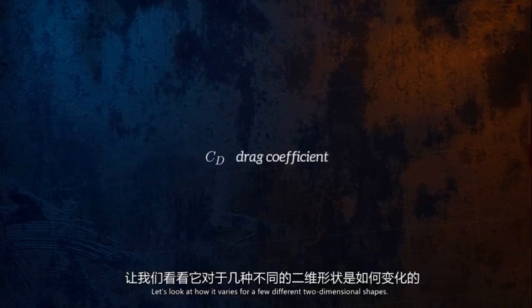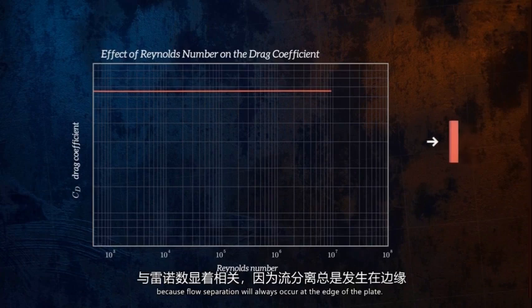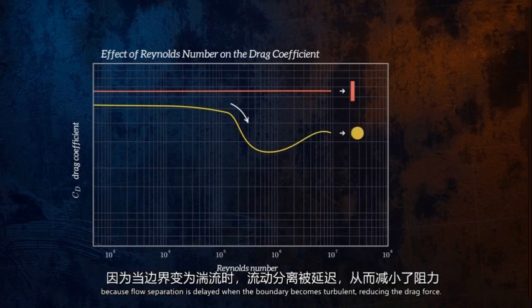Let's look at how it varies for a few different two-dimensional shapes. For a flat plate oriented at 90 degrees to the flow, the drag coefficient doesn't vary significantly with Reynolds number, because flow separation will always occur at the edge of the plate, and so, although it is a blunt body, it isn't affected by whether flow is laminar or turbulent. For blunt shapes like this disc, we see a large decrease in the drag coefficient at the transition between laminar and turbulent flow, because flow separation is delayed when the boundary layer becomes turbulent, reducing the drag force.